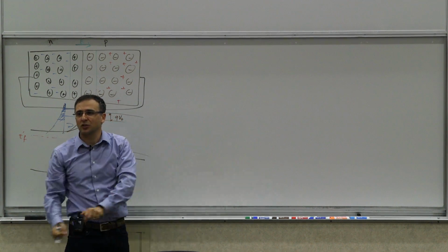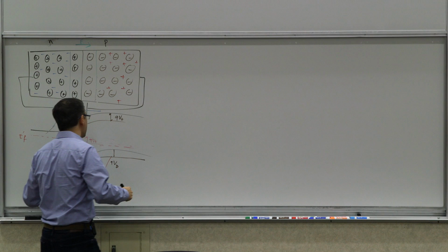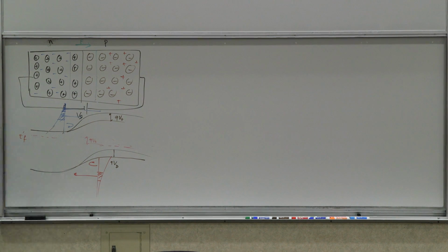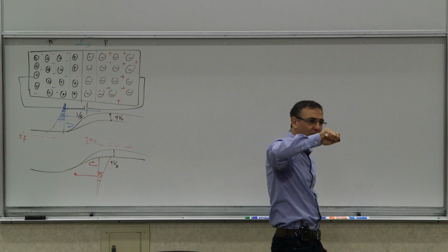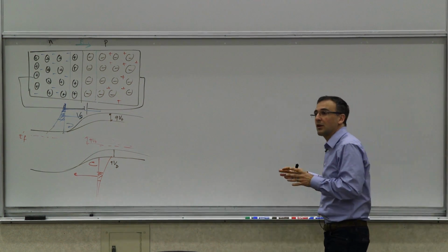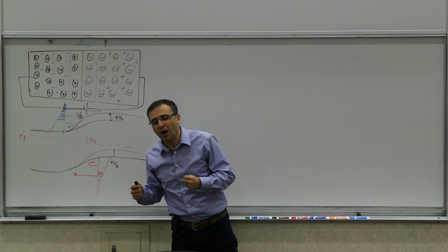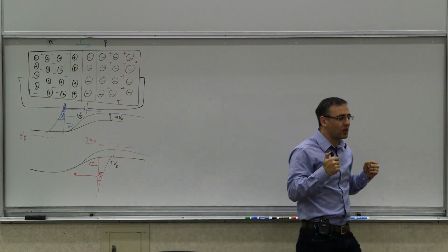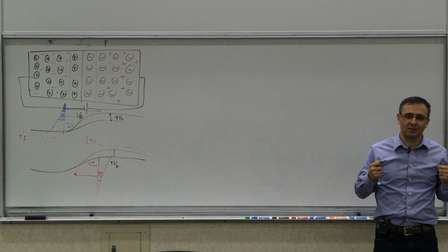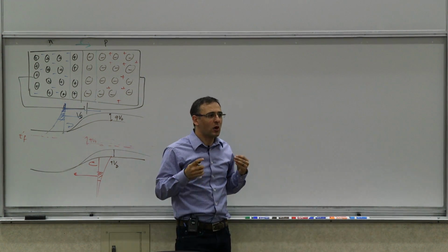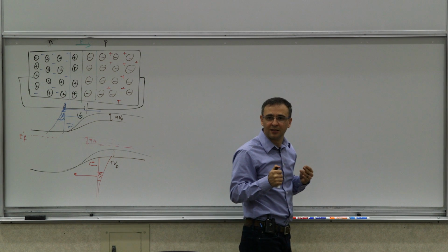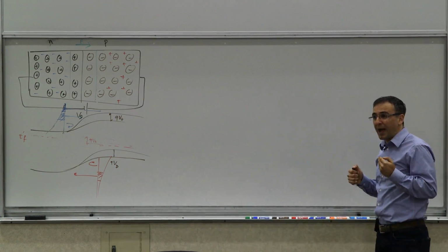Just the electrons will pour in, and the holes will pour in this direction. All you do is just need to adjust that knob. So it's a useful knob because you control the voltage, and then the thermal energy is doing a lot of work for you. And that's why the bipolar junction transistor has so much transconductance. When we compare it, for example, with MOSFET, you are really harnessing the thermal energy. And that's what makes it such a powerful device.